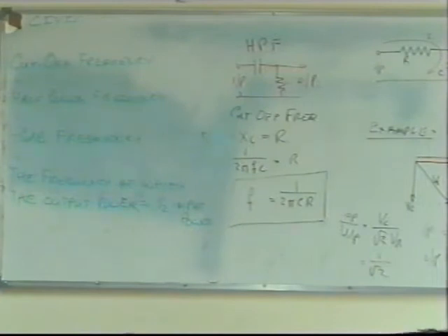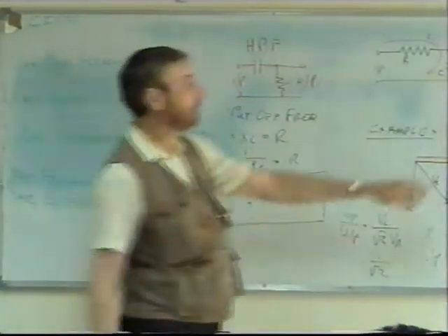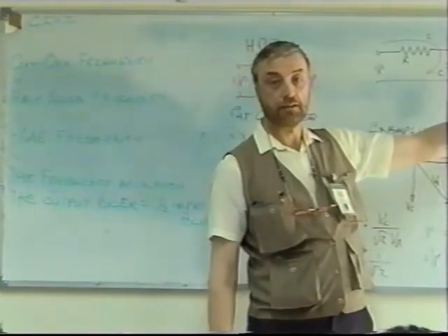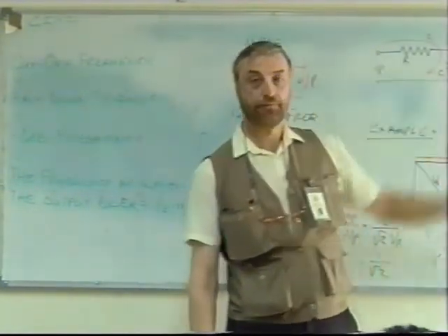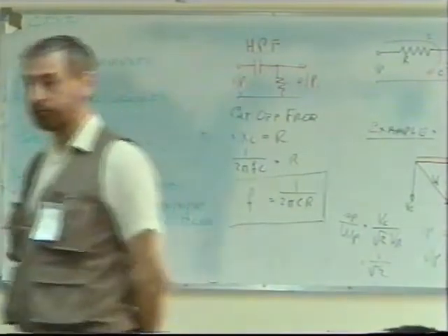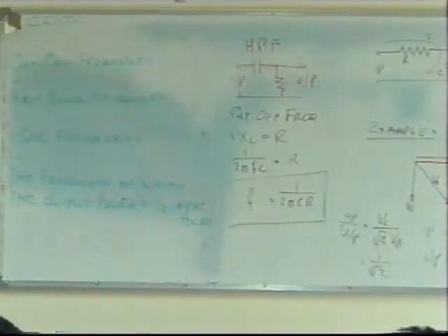That's why we can use decibels. It's the square of this, you see, so it becomes 1/2. We're using the square of the voltage. All of those mean the same. In a test, you might find any one of those three things, and you've just got to remember that they all mean the same thing: cutoff frequency, half-power frequency, minus 3 dB frequency.